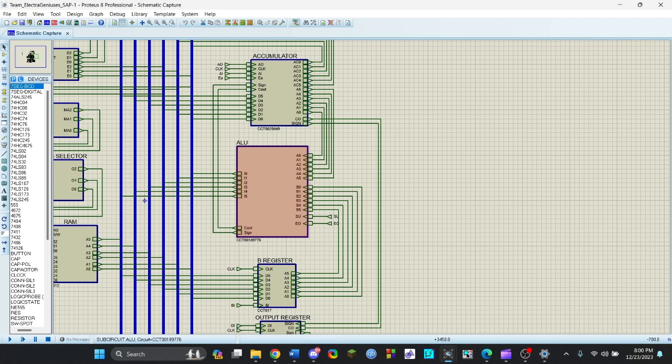And we can see there is another control bit, EO. EO puts the output from the ALU onto the bus. You can see that if the RAM output, or RO, is low, the output is disconnected from the bus. So that means that when the RAM output is low, or 0, the output is disconnected from the bus.